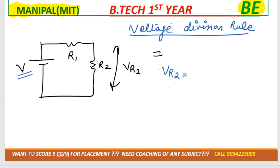How much is the total voltage for this particular case? V multiplied by the resistance of the branch across which we need the voltage, that is R2, divided by the sum of resistors which are connected in series. So which two resistors are connected in series? That is R1 plus R2. Okay,